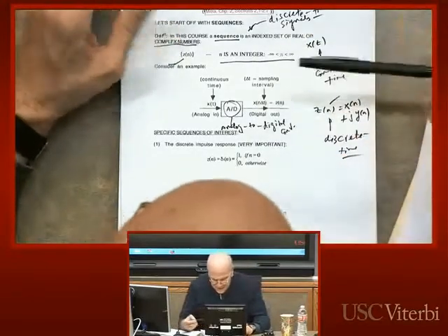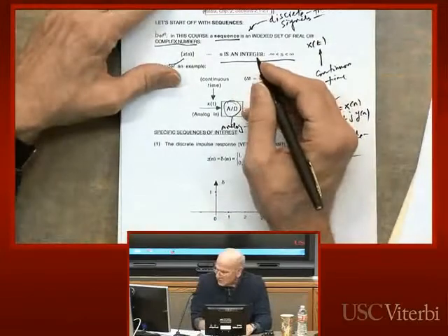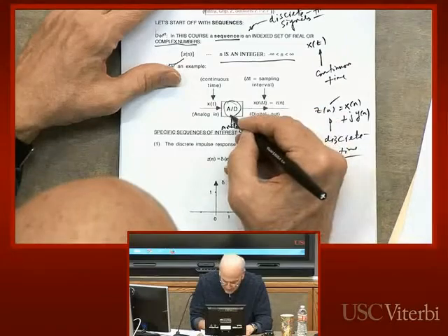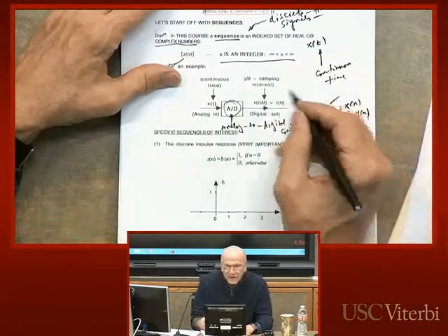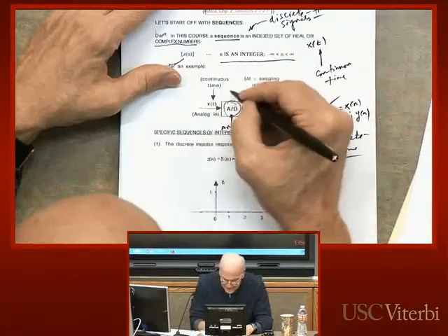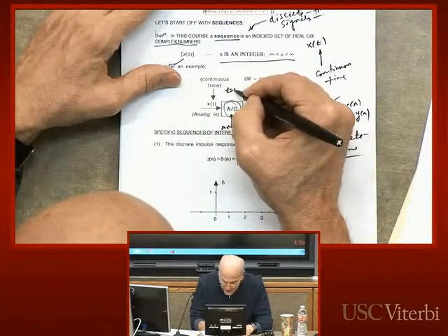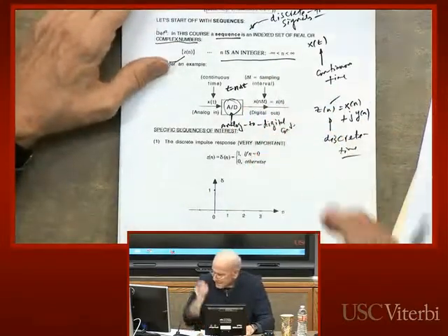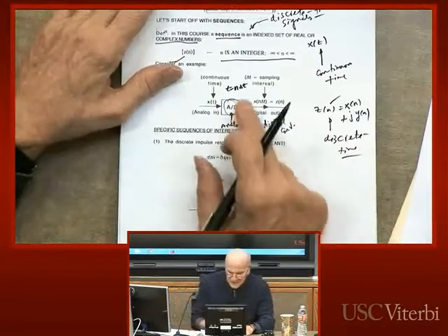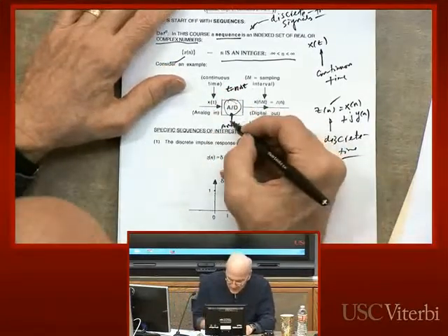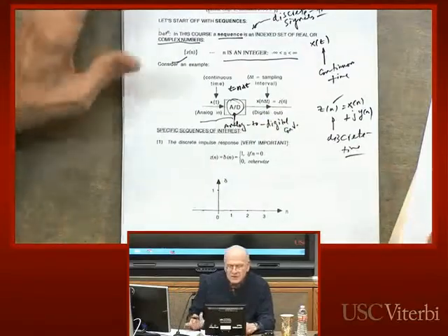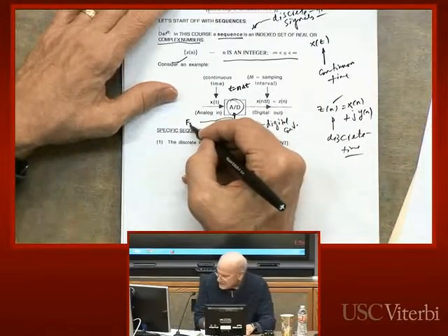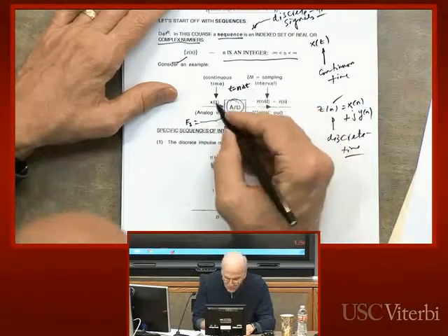Now in this case, what happens is you let t, oh, I should point this out too. t here will be equal to some integer times a delta t, okay? What is delta t? Well, that's typically one of the parameters that characterize an A to D converter. Namely, A to D converters require something called a sample frequency, f sub s. And this is called the sample rate.